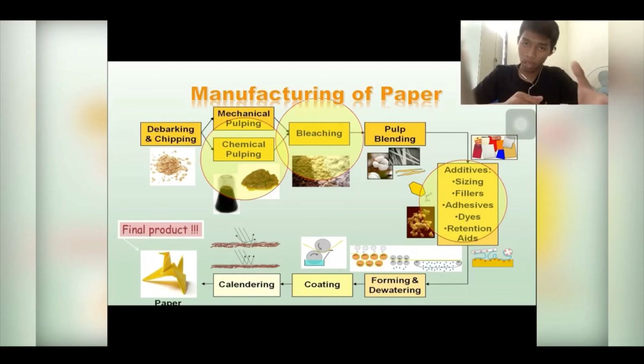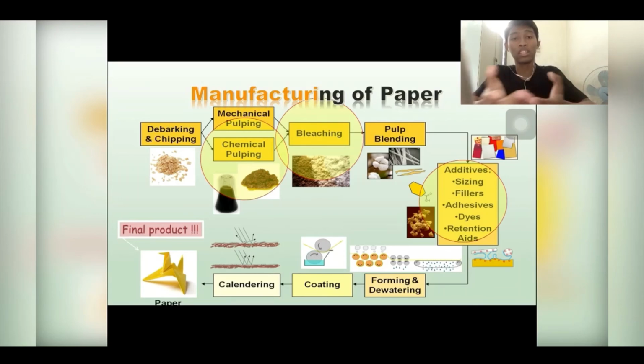The pulp is squeezed through a series of rollers, while suction devices below the belt drain off water. If the paper is to receive a watermark, a device called a dandy roll moves across the sheet of pulp and presses a design into it. Okay, so the next step is the removal of water. The paper then moves on to the press section of the machine, where it is pressed between rollers of wood or rollers of wool felt. The paper then passes over a series of steam heated cylinders to remove the remaining water.